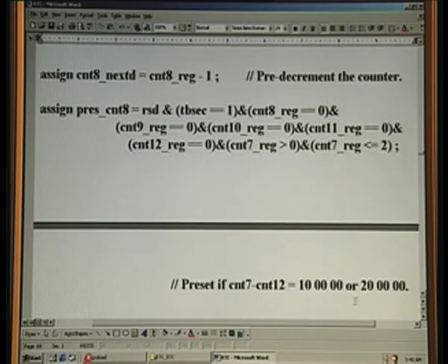If it is 1 0 or 2 0, then what should you do for counter 8? 7 8, right. 7, this is 8. So what should you do? We are in decrement mode, right. So this means decrement mode. Automatically it should go from 0 to 9. So you can't reset, you will have to preset. That's why preset has been used, right.